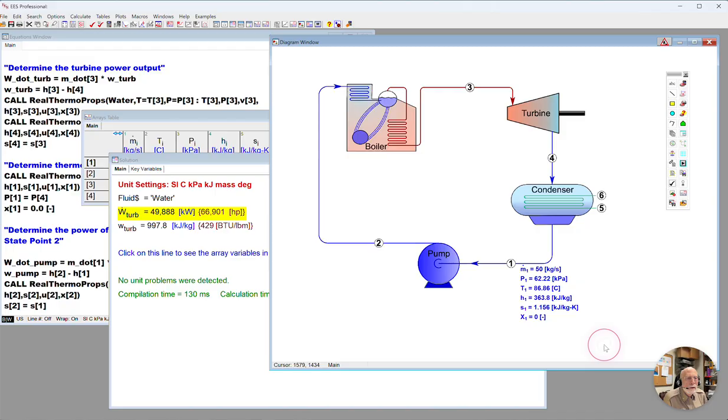So now what we want to do is we'll select that and we'll copy the whole thing. And then we'll paste it. And we're not going to paste multiple copies on top, because if we do that, we're going to drag all of them around. And we don't want to drag all of them around, because after we do the first one, we have to individually select for making a new group, because we can't do a batch select with an enclosing rectangle. So let's go ahead and just move it, copy and paste again.